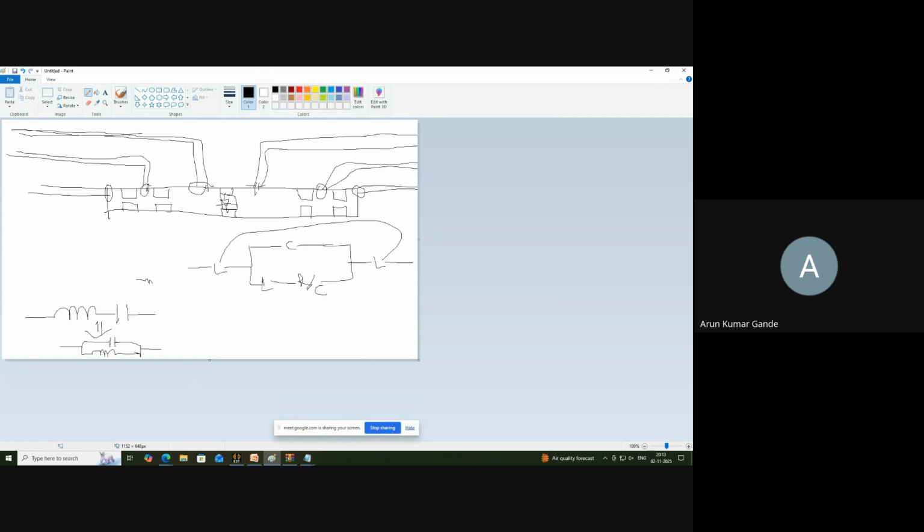So once you convert this, let me assume that this is in off condition. So you have L and C. You can convert this series LC network to parallel LC. And now what you have is these two inductances. You have L, followed by a C, then a C, and then an L, right? So you can add these two capacitances because they are in parallel. Effectively, you have an L, then a C, and an L. So this is the equivalent circuit that you have in off condition.